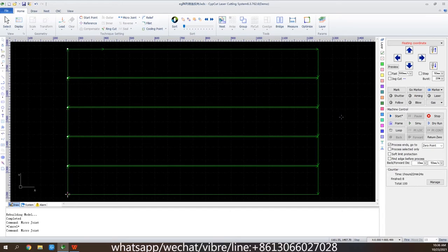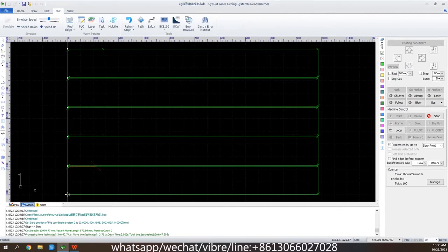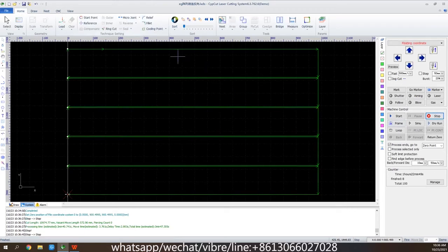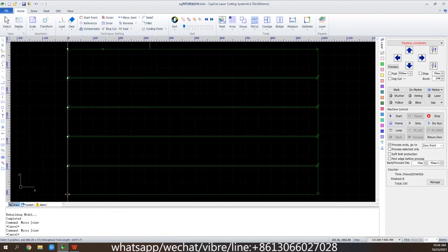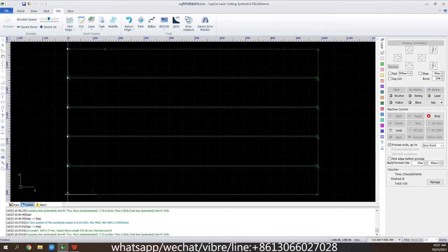And besides, the default cutting path goes clockwise. When we come to the bottom line of the second oblong, the sheet will vibrate for lack of support. To solve the problem, we use the feature reverse. We use the reverse to change the direction of the cutting path. So now, as the sheet gets better support, it will stay steady while being cut.